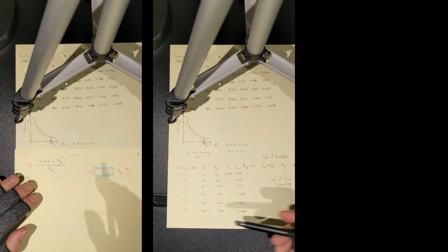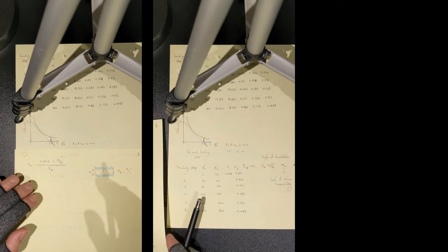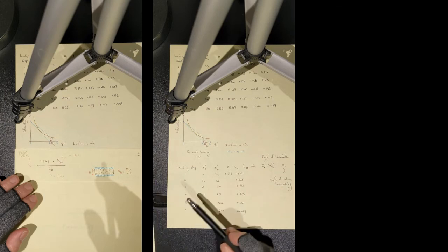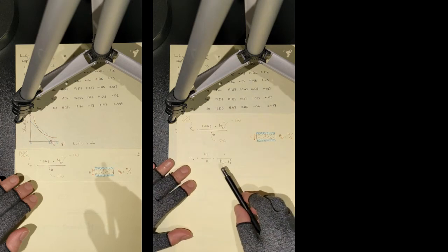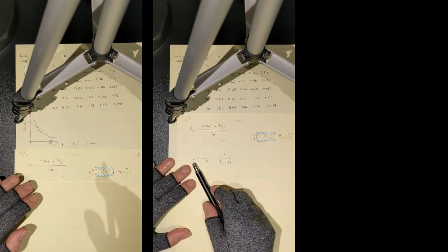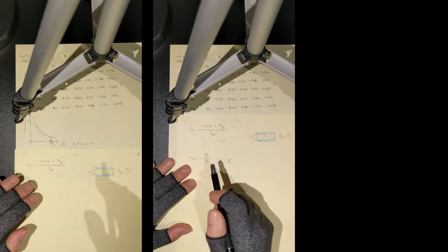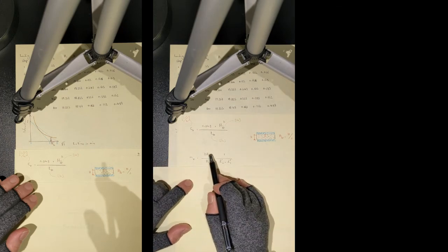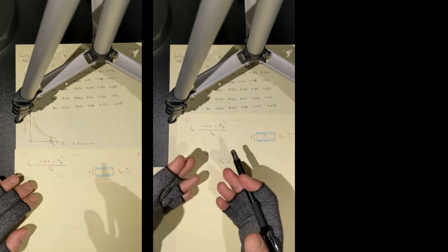So it is a very important parameter, M sub V, coefficient of volume compressibility. Let's see how we can determine coefficient of volume compressibility for each loading step. Look at this very simple equation. M sub V is equal to delta H, how much the dial gauge is showing you at each loading step,